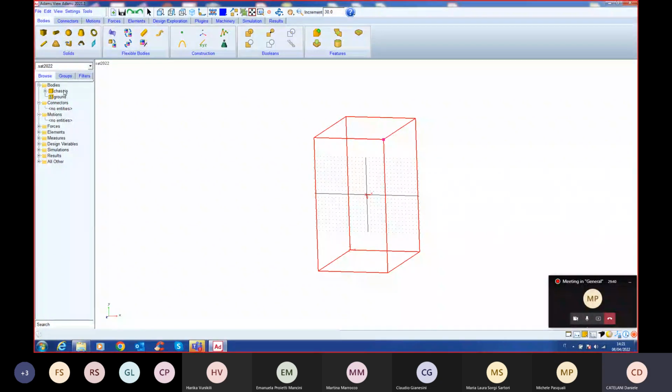This body has 6 degrees of freedom at the moment. There is no constraint. So Adams writes 6 differential equations for you. And if we simulate this body, if we have forces applied to the body, it can fly in the 3D space. But we want to make this body fixed to the universe.